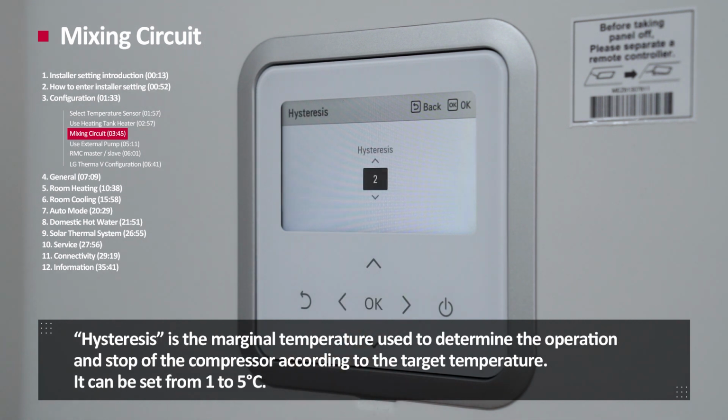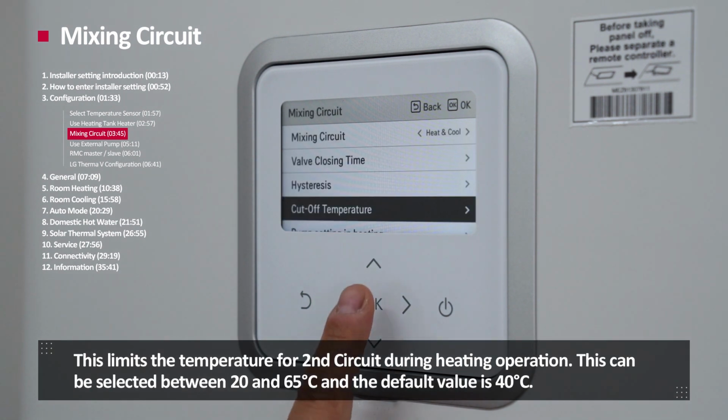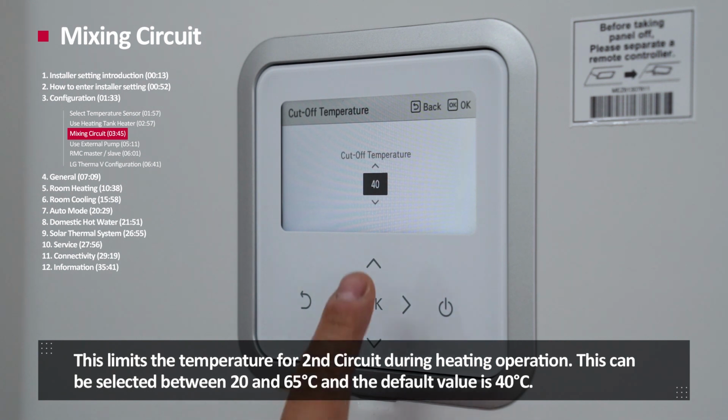Hysteresis. Hysteresis is the marginal temperature used to determine the operation and stop of the compressor according to the target temperature. It can be set from 1 to 5 degrees Celsius. Cutoff temperature. This limits the temperature for second circuit during heating operation. This can be selected between 20 and 65 degrees Celsius. And the default value is 40 degrees Celsius.